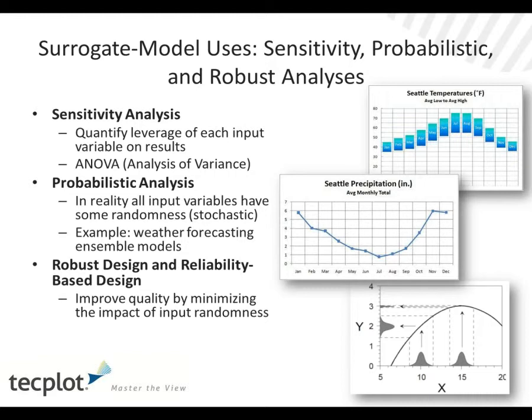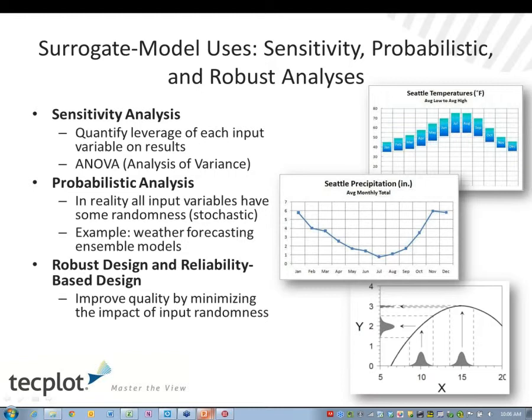Sure. This is all based on the surrogate model, which is really a representation of the data between your points. So this could be a fit of a function, or it could be a more complicated model like a Kriging model, a statistical interpolating technique between the points in your metadata space, your n-dimensional space. And so in that space, you might want to get an idea for the sensitivity of your outputs, your results, to various inputs.